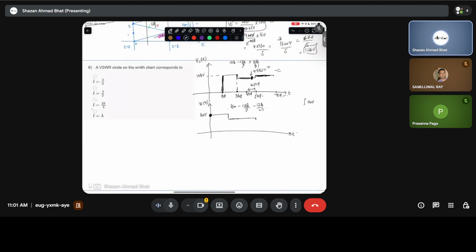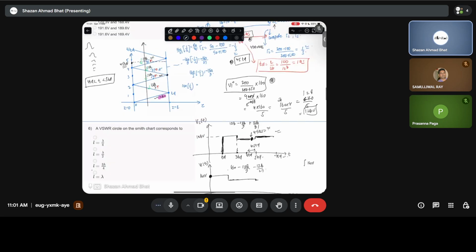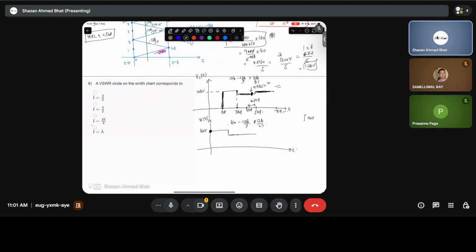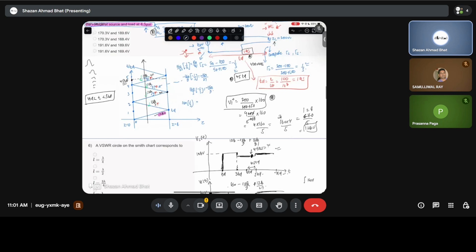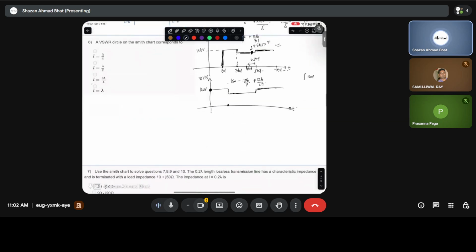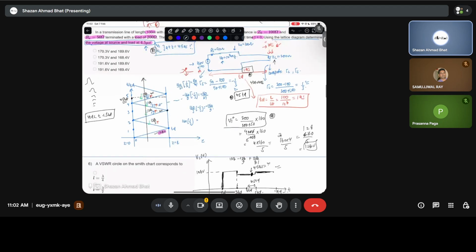So it'll look something like, I guess should be plus, and yes, so if this is 0, this is 2TD, this thing is 4TD, this thing will be 6TD, which we don't care. Then this will be 5TD. We want to find the voltage at this point, which will be 4.5TD. So this will be the exact 4.5 microsecond point, and you need to compute this particular value after solving the fraction. So that will be the exact answer of this.